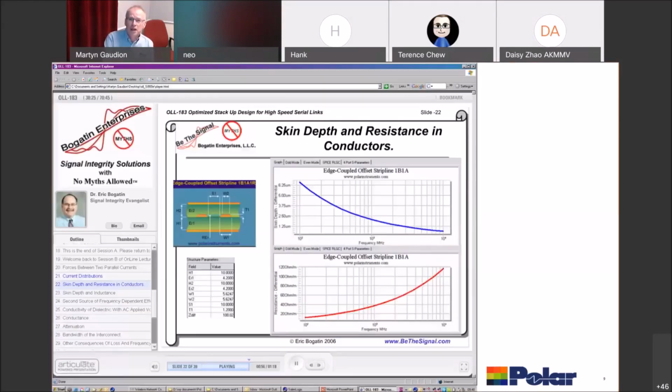On the next slide, we can see graphically that as we increase the frequency, the depth in the copper reduces. Let's just highlight this. At 100 hertz, you've got 6 microns, then 2 kilohertz, 10 kilohertz, and so on. And approximately, it's around about a micron at a gigahertz.